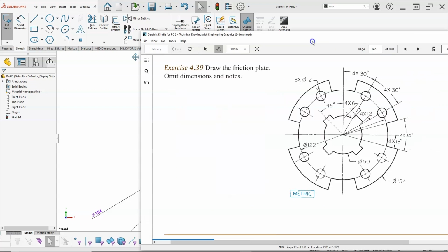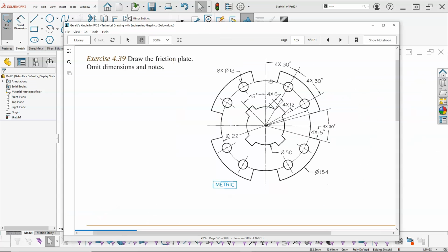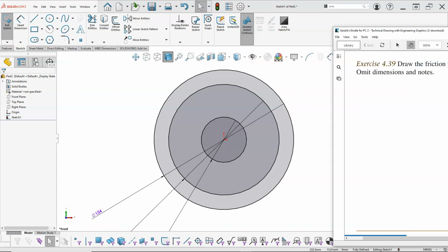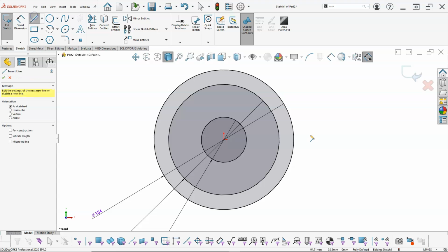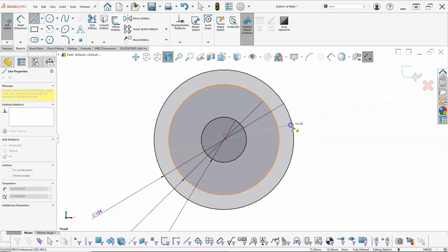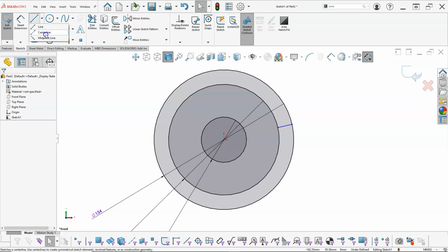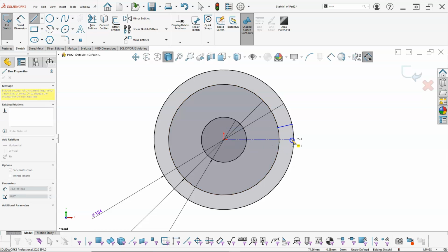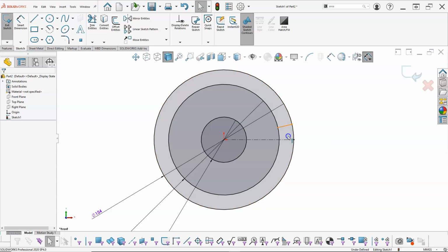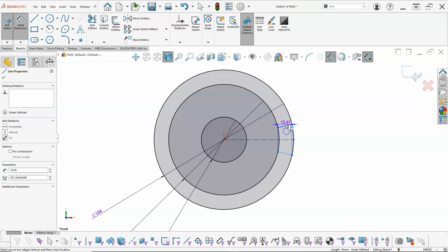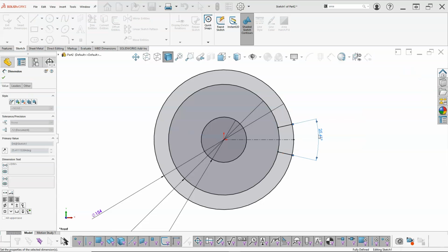Okay, so our lines from here out are going to be, looks to be from the center out and then 30 degrees across. So that being the case, I just want to make sure that I don't pick up a tangency, that I end up with the geometry. Probably will need a center line at least at this point. And then I can just go ahead and mirror that over. So select, Control, Select. And because of the symmetry across the center line, we only need the 30.